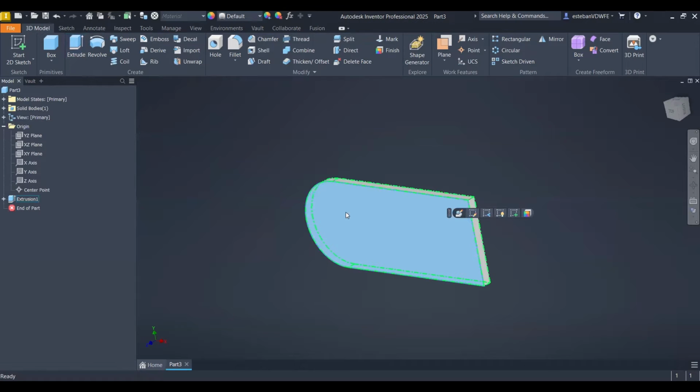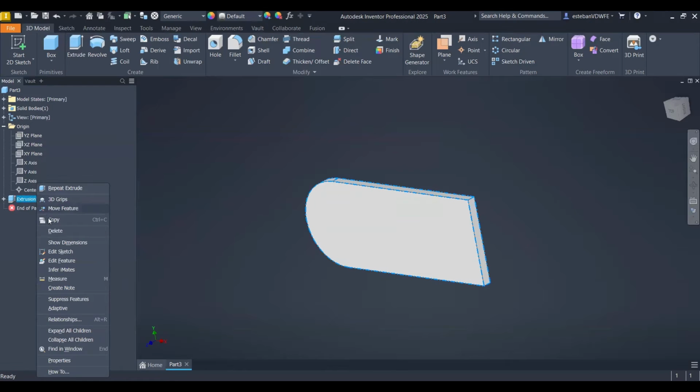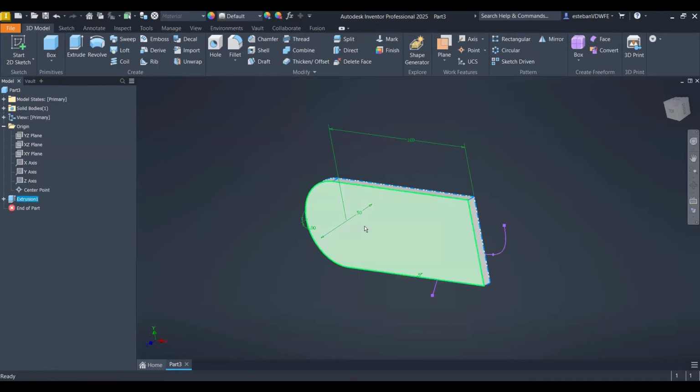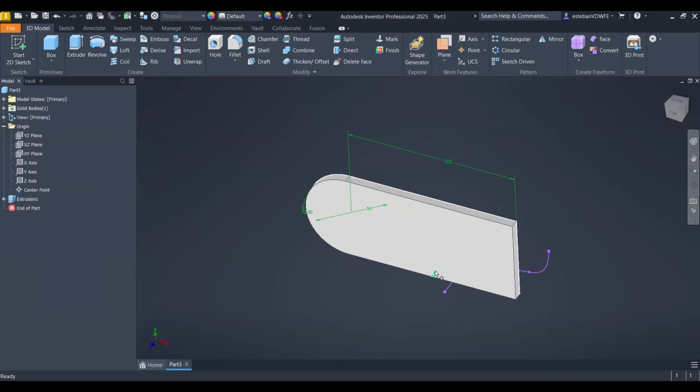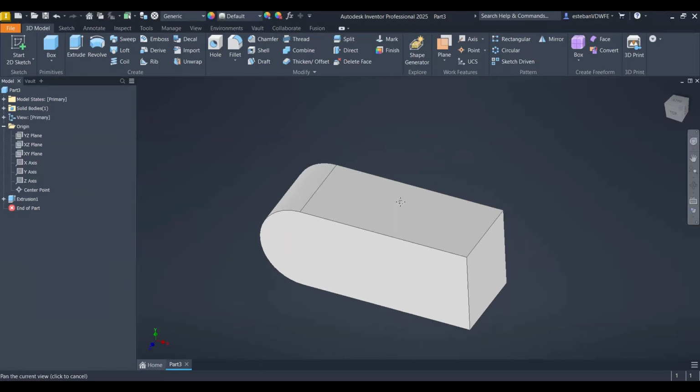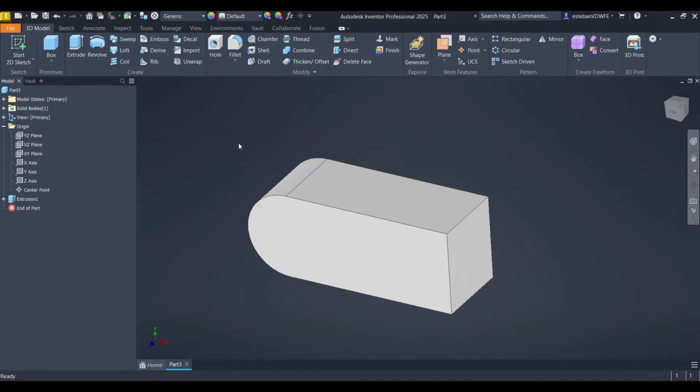You can change the dimensions in SolidWorks. People just double click and they have the dimensions. Well, in Autodesk Inventor now you have many ways to show the dimensions. One is selecting the feature here at the left in the model tree and clicking on show dimensions. So for example, I click here, I have this one was 45 millimeters. Click update, there you go.